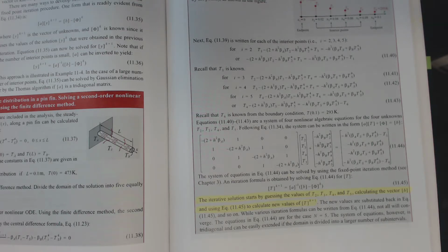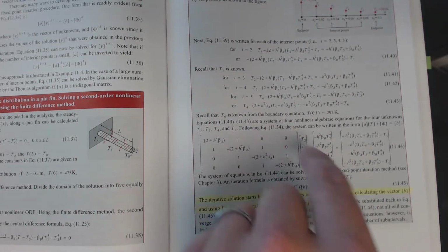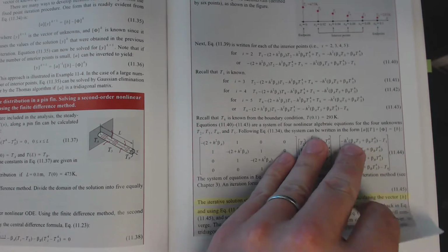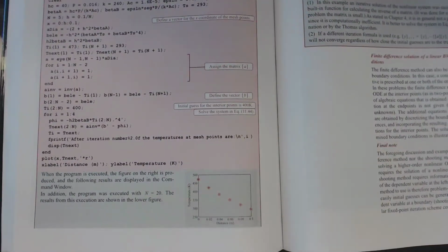So this defaults back to iterative solution methods for nonlinear equations. There's very little incentive to put it into a matrix form here. You might as well just take these equations above, solve them for the individual T variables, find an arrangement or a level of relaxation that makes it stable, and enjoy your solution. The answer comes out not all that different. There's the answer down there, bottom right.